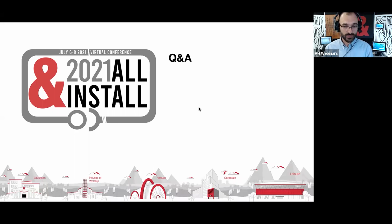There are a few limitations though, and there are some benefits to having a dedicated hardware echo cancelling module. The first one is the multi-microphone scenario we described. The other one is the fact that typically the length of the filter, or the length of the tail, if you like, for those filters in the cloud processing is normally optimized for something like a person talking into a laptop or a portable device or a mobile device, and not considering longer reflections from a larger room with maybe condenser microphones or conference microphones, ceiling microphones, and so on. So that's where a hardware solution can become a lot more attractive.